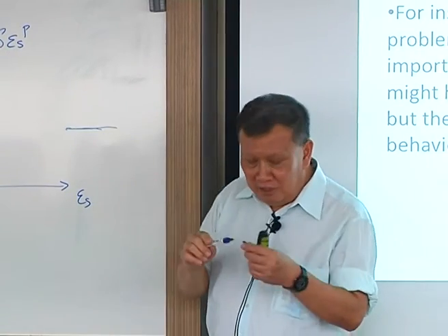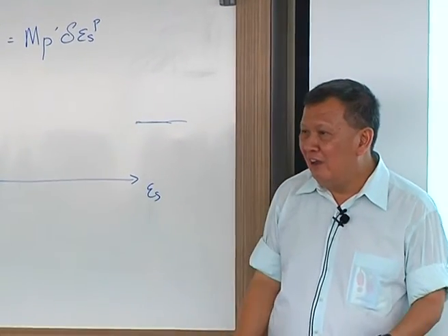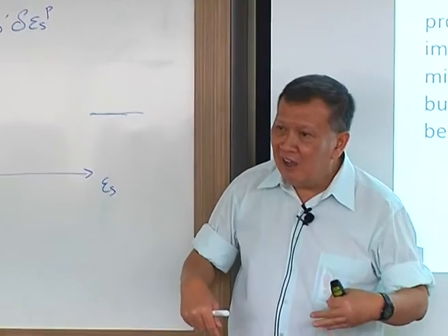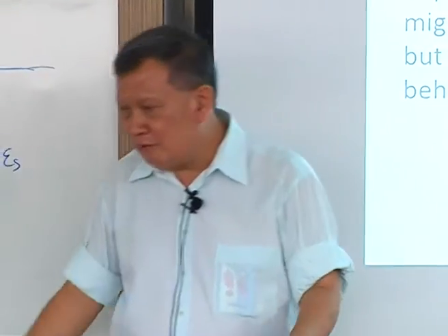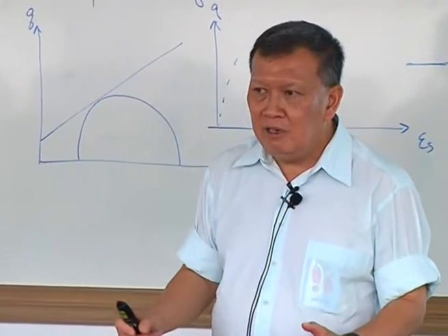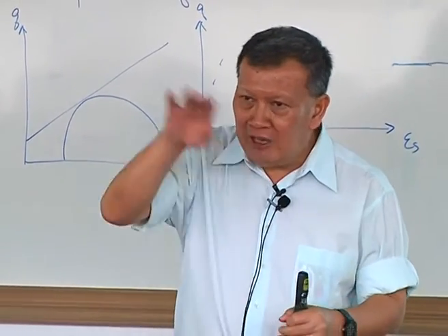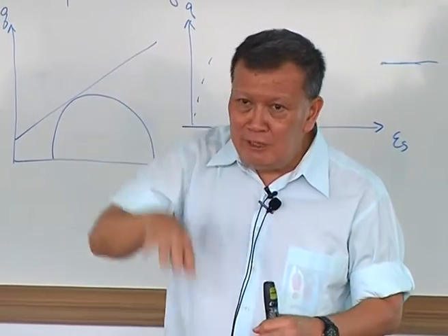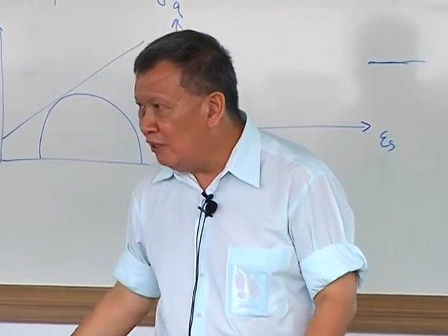So in that particular problem, we know the factor of safety was less than 1, because the thing actually collapsed. Right? So we know that this is the most important thing. On the other hand, if you have something where the factor of safety is reasonably good, you look at it, it is a stiffness control problem. I don't care whether you use a hyperbolic or a representative E50, make sure you capture your stiffness reasonably well, and your answer is good.